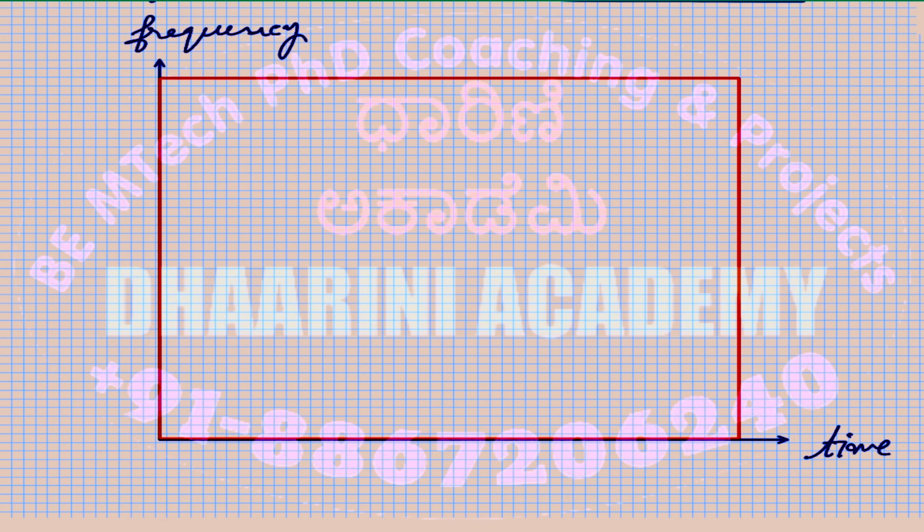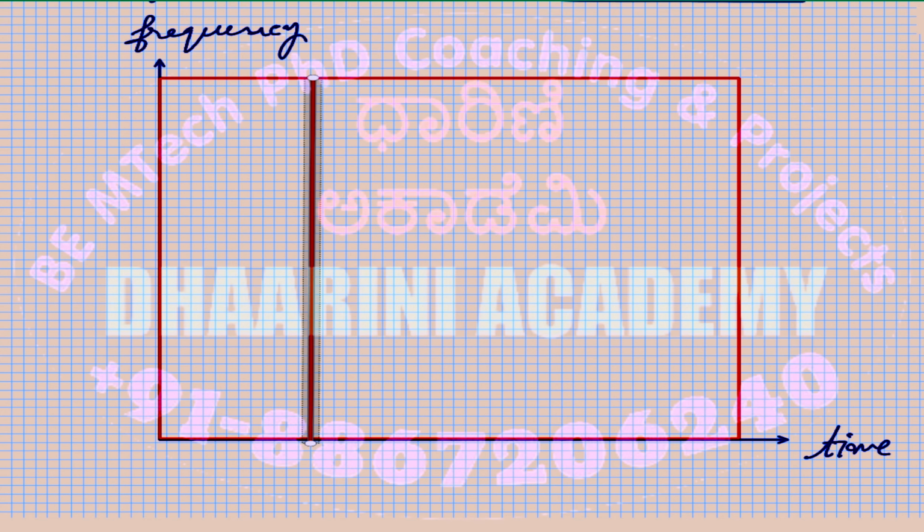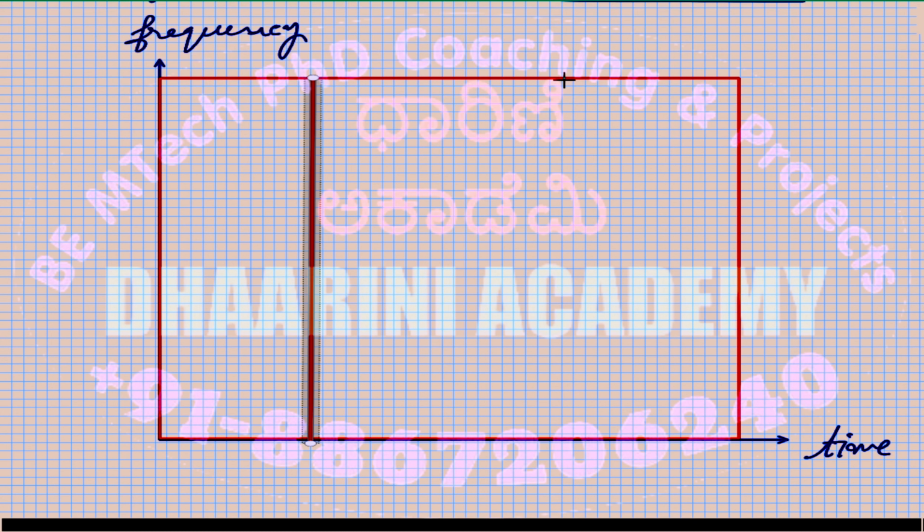So what we do, we divide this in terms of time. You see the division happens in time. So this is a time slot. Correct. So this is time slot number one, and maybe I'll divide this like this. And again, just to avoid the timing errors, we'll introduce the concept of guard bands.